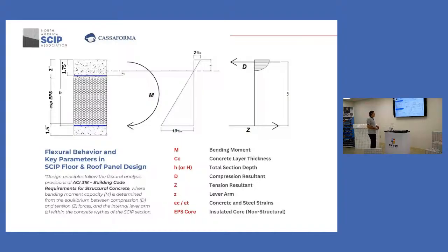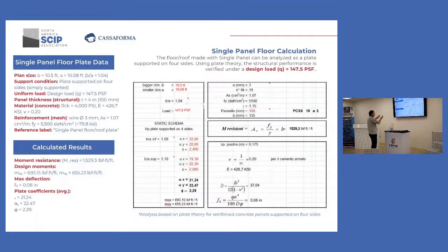So here, in a simple calculation, what we will do is take the numbers that come out on the moments that we have on X and Y, and we will see how they match the quantity of steel that I have, keeping in mind the lever arm, because the lever arm is what will drop the quantity of mesh that I require. So that's basically what we have.